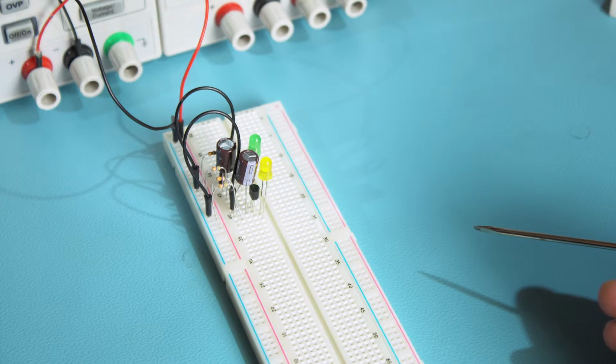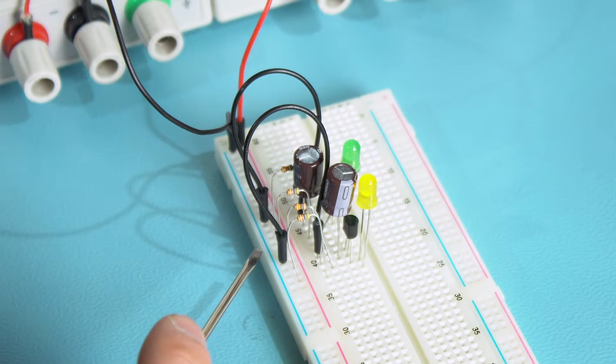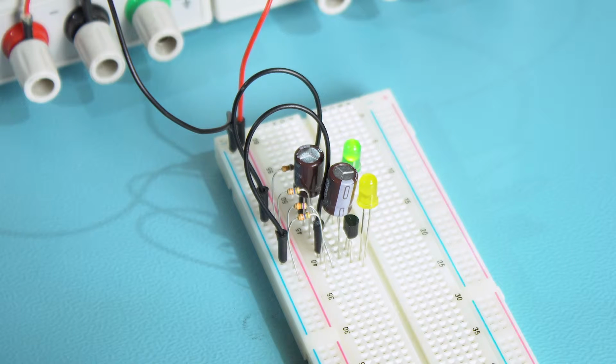If you change resistors R2 and R3 to those with a larger value, the system will slow down. Let us consider what will happen when the elements are asymmetrically chosen. In this case, one of the LEDs will shine longer than the other.